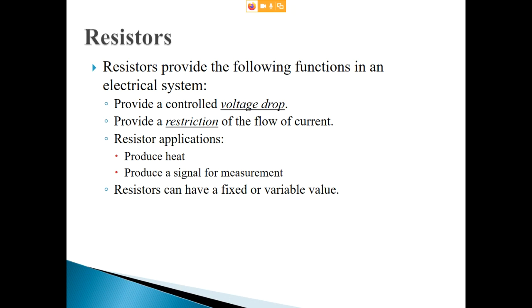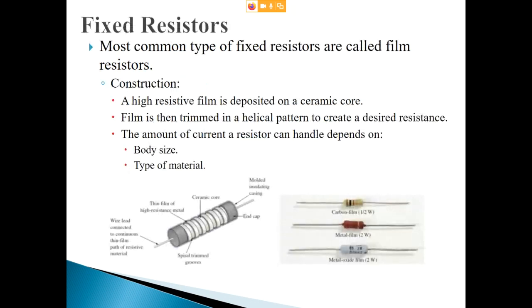When you connect that up, the first one is basically going to drop 50 of those 100 volts. And then the second resistor is going to drop the other 50. So that when you get down to the bottom, you've got 0, which would be your ground. But remember, you have to have a complete circuit for that current to flow.